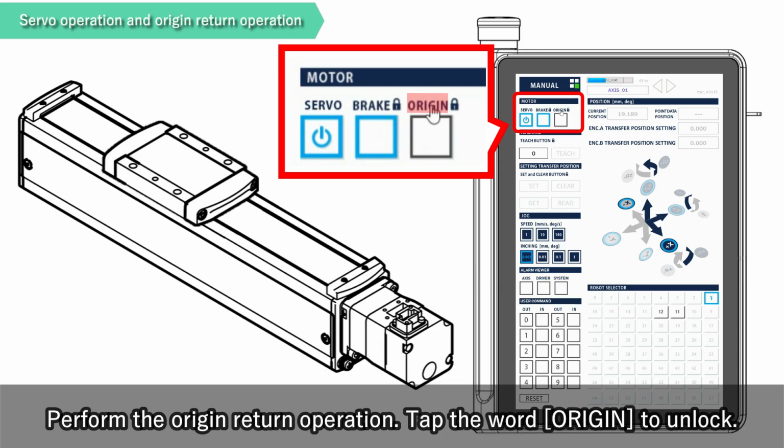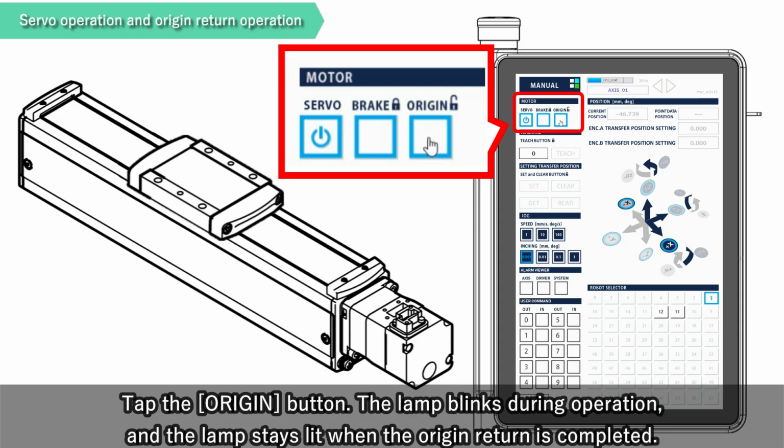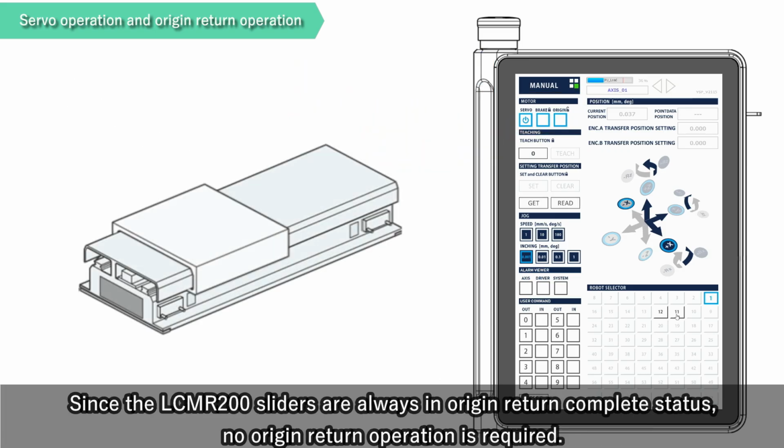Perform the origin return operation. Tap the word origin to unlock. Tap the origin button. The lamp blinks during operation, and the lamp stays lit when the origin return is completed. Since the LCMR200 sliders are always in origin return complete status, no origin return operation is required.